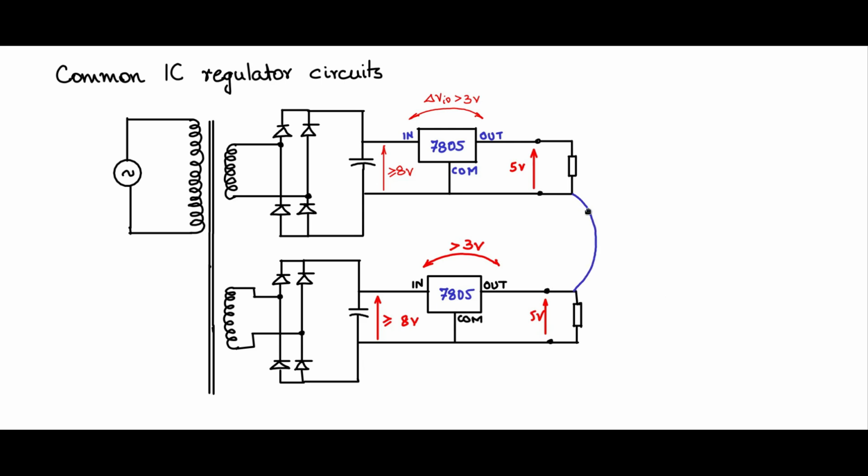So what you do is short the minus of this to the plus of this, and indicate that as the ground or the zero potential. Now all your further circuits should consider this as the zero potential or the circuit ground. Then with respect to this node, this point will be at plus 5 volts. And with respect to this ground, this point will be minus 5 volts. So this way, this power supply together, shown like this, acts like a dual positive negative power supply.